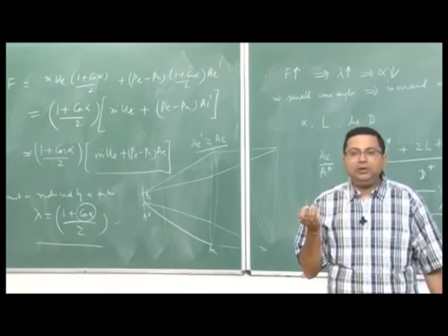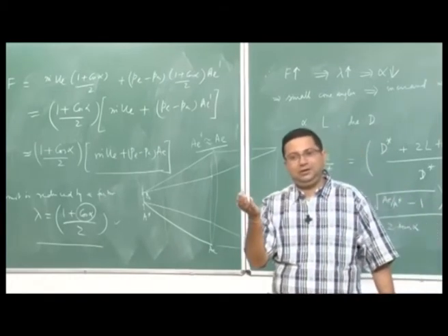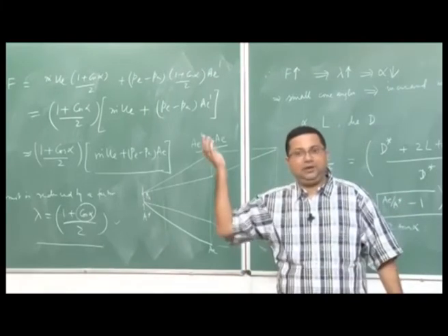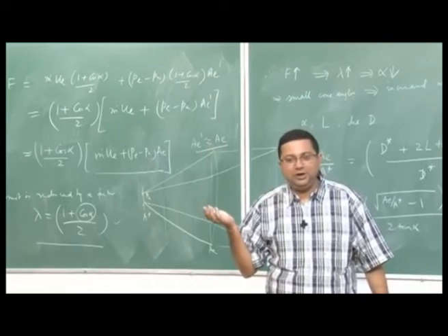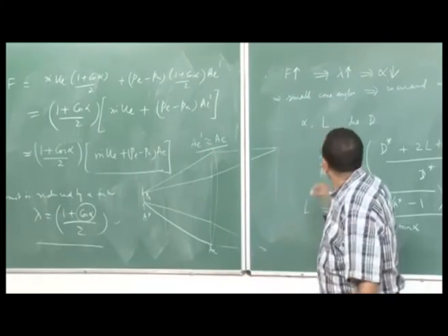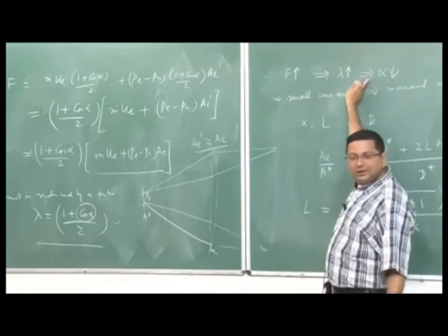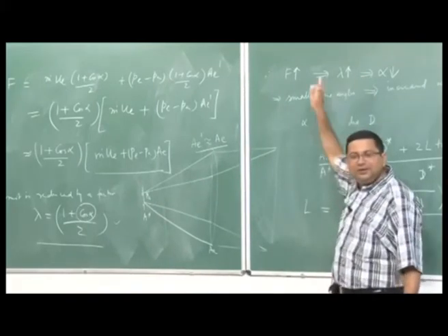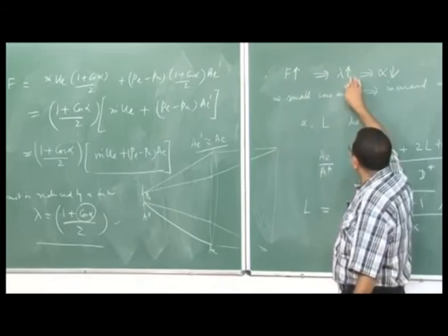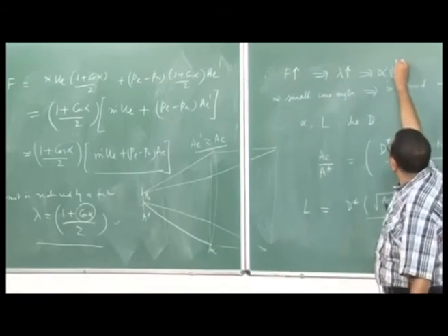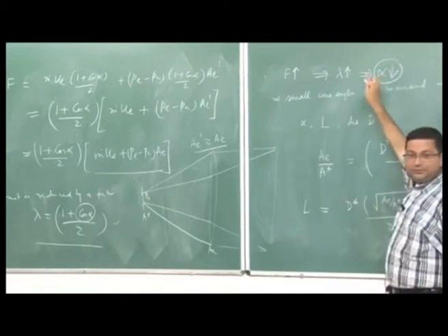We may not be able to do it for the entire nozzle, but even if we do it for a section towards the exit, then we have improved the performance a lot. And in that case, since we are not changing lambda, we do not need to change alpha, it is a straight section now. So, this advantage we can get without having to reduce this alpha.